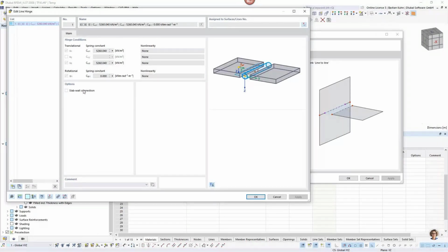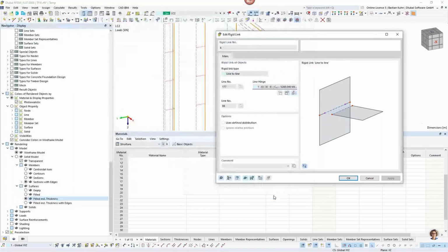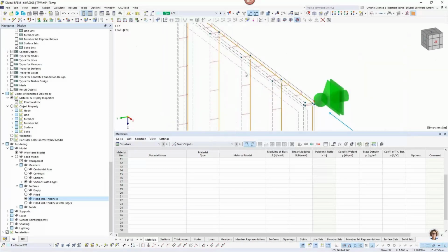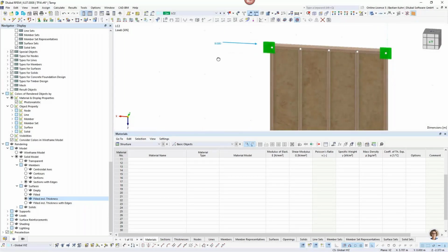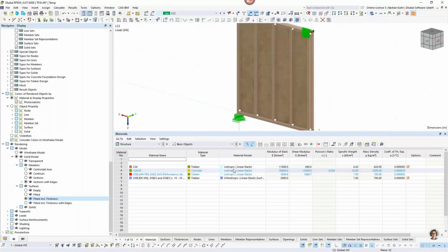I also told you that we should remember this longitudinal stiffness, where if I had chosen just to have the stiffness in UX direction, my UZ value would be 0 in here. So that would also be possible. Okay, this is the generated hinge, and it's generated once again between each beam and the OSB planking. I will put on the rendering again. So here this way, it's probably a better visibility.